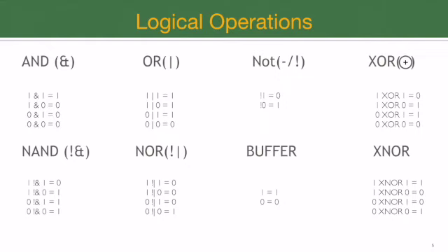I am not going to cover a lot of details of these operations, but just to give you a quick idea, the NAND operation is actually the reverse of AND operation. So if you look at the truth table for NAND operation, notice that wherever a result of 1 is generated in case of AND, the NAND generates the reverse of that result. So the NAND operation between 2 bits that are 1 produces the result of 0. In all other cases, the result is 1.